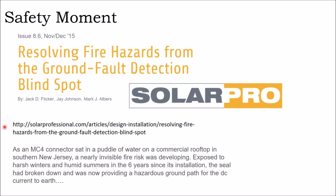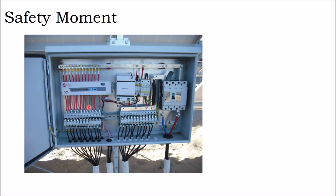So imagine you have a puddle and you have a circuit, and the solar conductor is now dropping down in that puddle. And now your puddle is energized. But it's not connected to ground. Water on top of a TPO rooftop, that TPO rooftop is insulated. So now you have a ground fault. And where can that puddle occur?